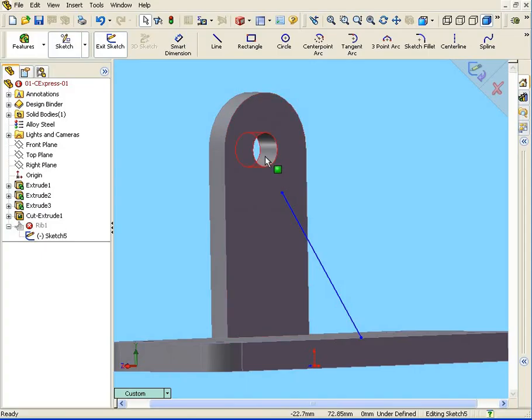If we extend this line, it'll actually go through that hole and won't intersect with the wall. Unfortunately, intersecting with a wall is one of the requirements for creating this rib, so we will need to revise our sketch a little bit here, since that's why SolidWorks had given us that warning message a little bit earlier. And this concludes our tutorial on optimizing parts in COSMOSXpress.